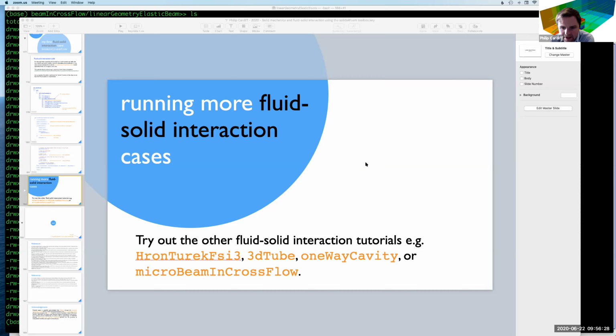So what's the limit in this approximation? There's no limit in accuracy if you get it to converge. The only limit might be if you have very large deformations, maybe convergence could be difficult, and maybe a coupled solution methodology might help speed it up, like a Newton-Raphson method or something like that, if you're using this implicit-explicit scheme. There are solid models I didn't talk about here, like fully explicit ones, which don't have convergence issues, but are slower, I guess.